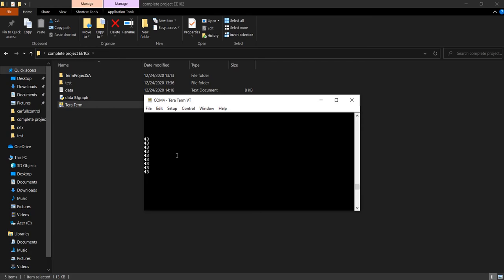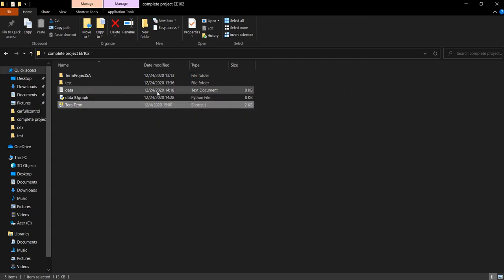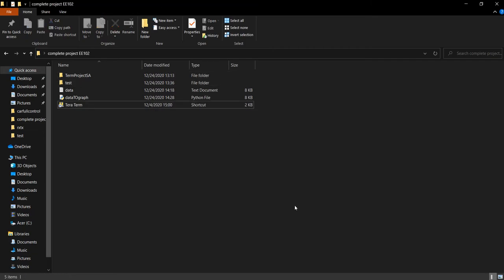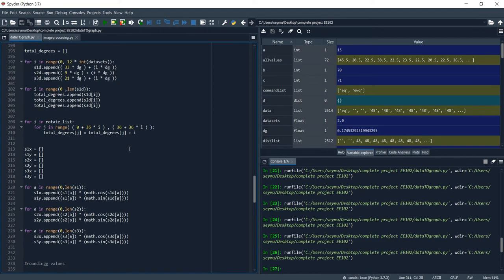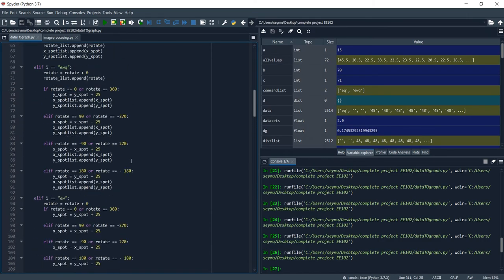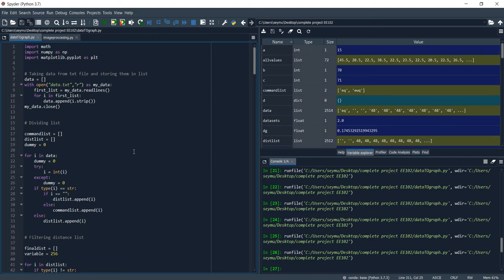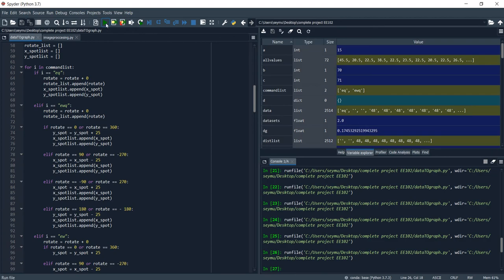Let's just stop it and I will show you my Python code which actually filters it. I have scanned a box two times. I scanned it two times and moved the car forward for the second scan, and I have my Python code here which filters the unnecessary data and removes the false data. That false data comes from HC12 modules, because sometimes that module can have data loss issues, so that's why there are some problems. But anyway, this code filters it, so let me just run it.